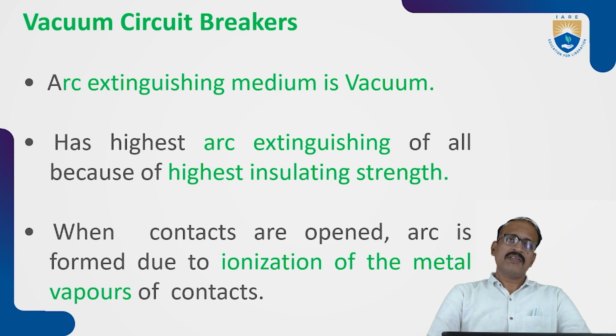The fault current will be at such a high level that the contacts, which are made of metals, will generate vapor, and that vapor is also ionized because of the power of the fault.